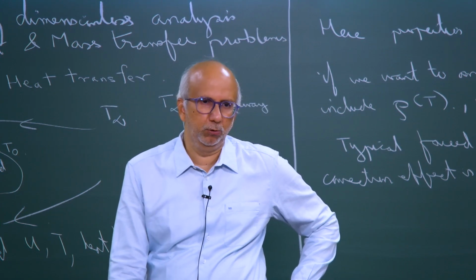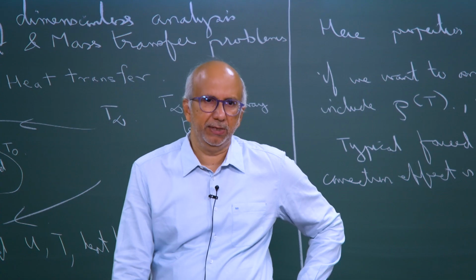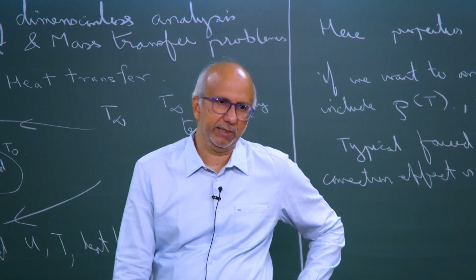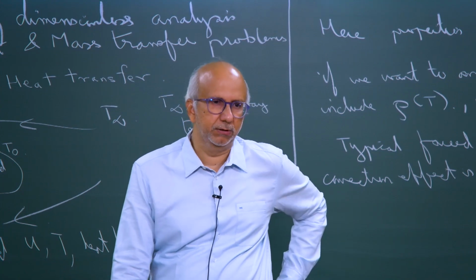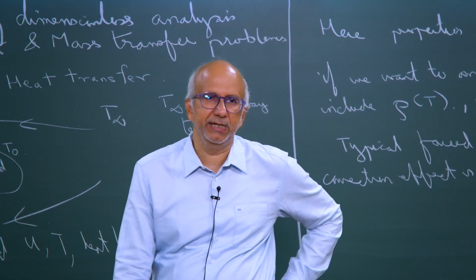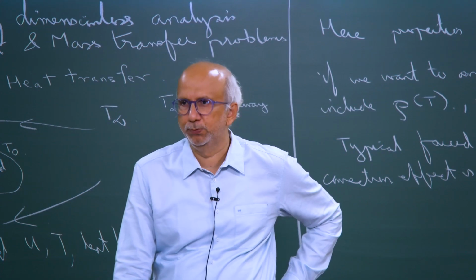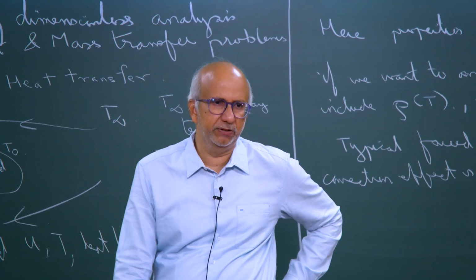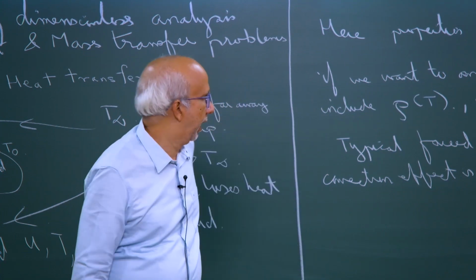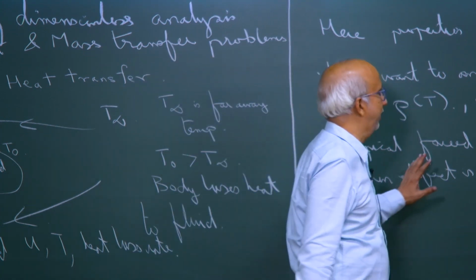So, it is not that we are doing something arbitrary, you can do a thoughtful analysis. Okay, how much is the viscosity change in the temperature range of interest to you. If it is not significant, then you say I will assume constant and go, or take an average value and go. Okay. So, this is typically what is done.